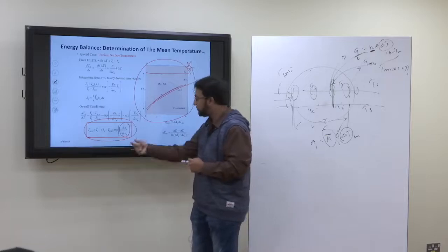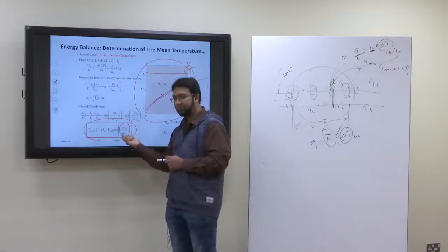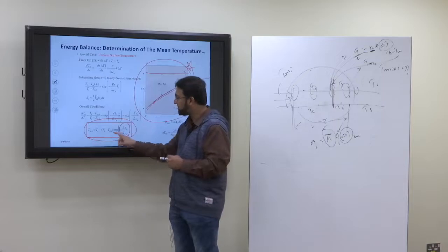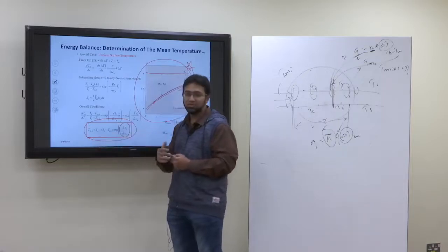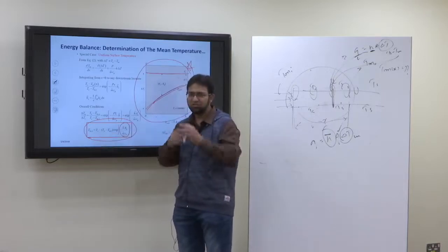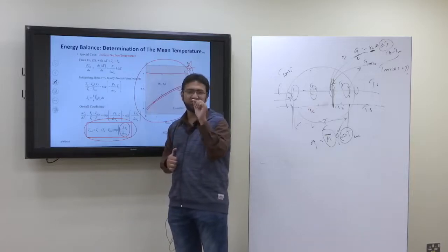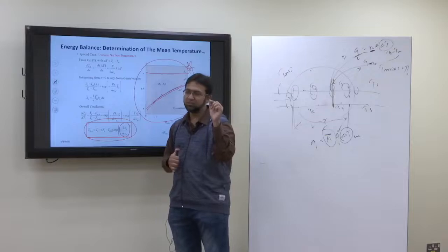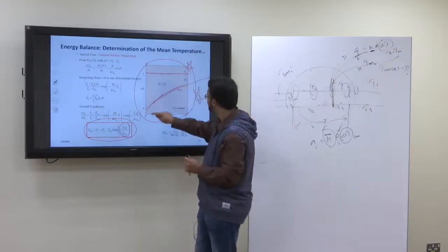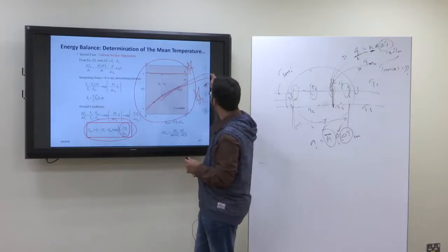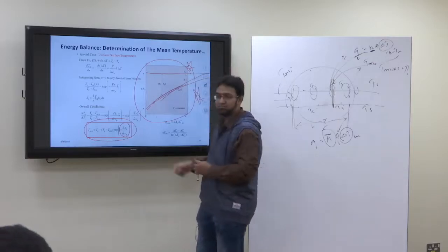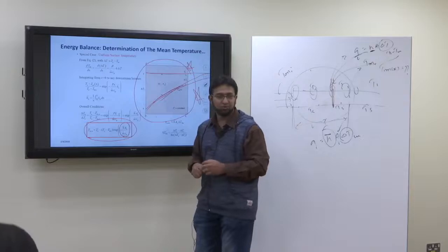And you will see that if you put this term equal to 5, approximately Ts will become equal to T mean outlet. Very close. T mean outlet would be less than 0.1% different from Ts. So this will become almost very close to Ts at NTU about 5.